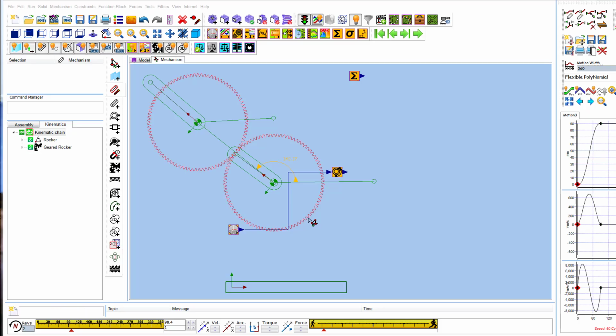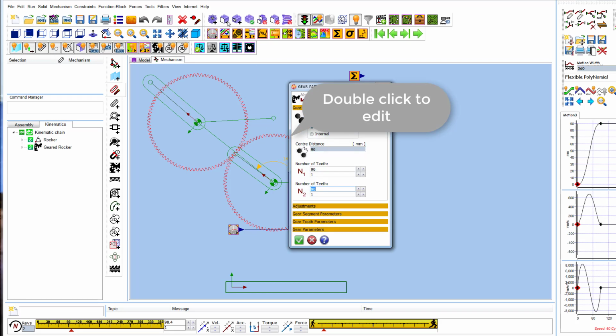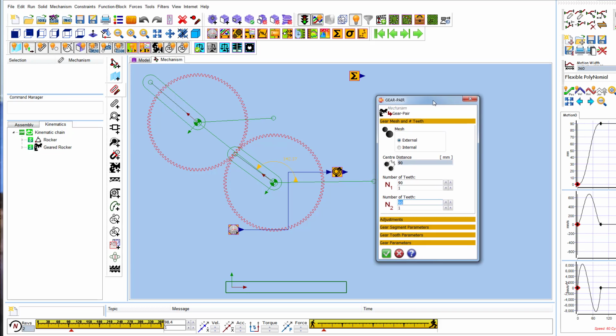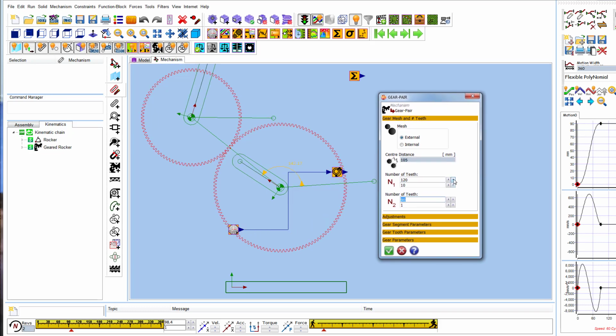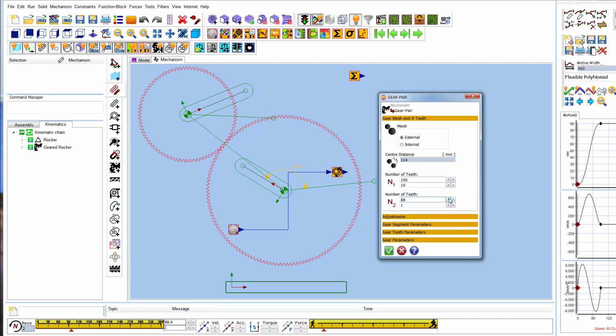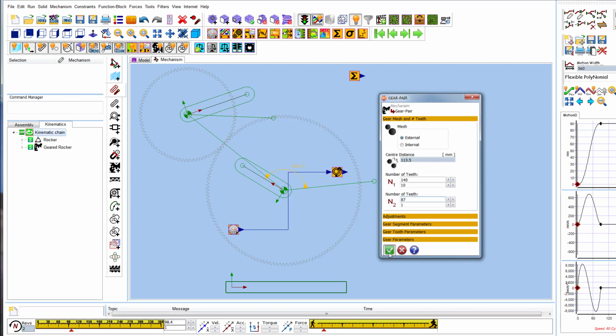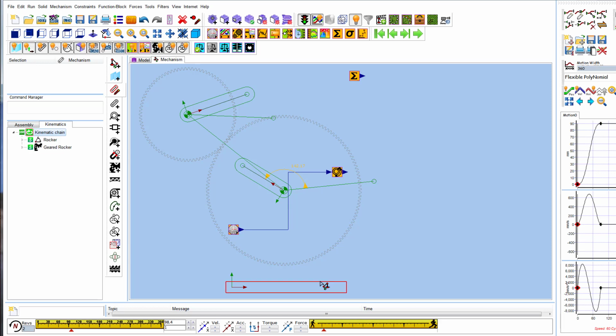If you want to edit elements in MD Pro, then double click on them in the graphic area and usually an editing form will come up. With gear pairs there is a lot you can edit, main items being tooth count and module. The center distance will change to suit the parameters you want because the gear pair controls it. You cannot edit it directly.